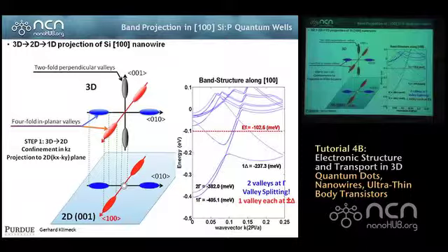That sheet of highly dense impurities acts like a semi-metal. So at the Fermi level, you have a ton of states that can conduct, just like a metal. And you do that in the middle of a semiconductor. Okay? So you create a local metal that has so many electrons in it that it behaves like a metal in an atomically thin sheet, which is a kind of cool thing if you can start to control that.